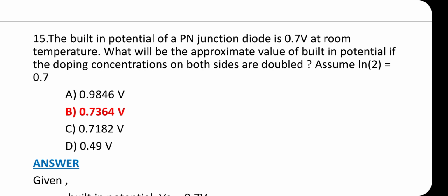As the N-type material has lost electrons and the P-type has lost holes, the N-type material has become positive with respect to the P-type. Then the presence of impurity ions on both sides of the junction causes an electric field to be established across the region, with the N side at a positive voltage relative to the P side. The problem now is that a free charge requires some extra energy to overcome the barrier that now exists for it to be able to cross the depletion region. The electric field created by the diffusion process has created a built-in potential difference across the junction with an open circuit or zero bias potential.